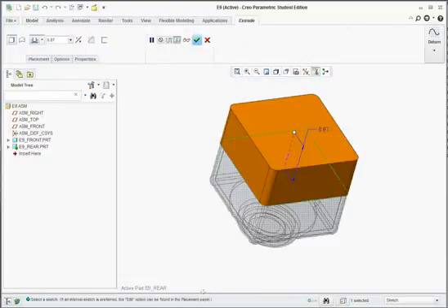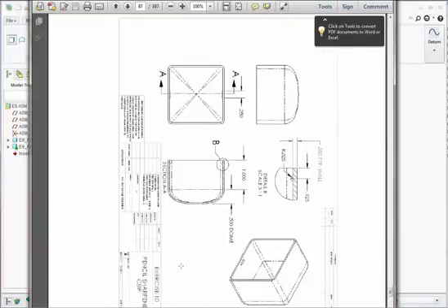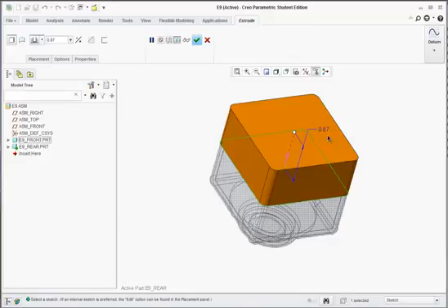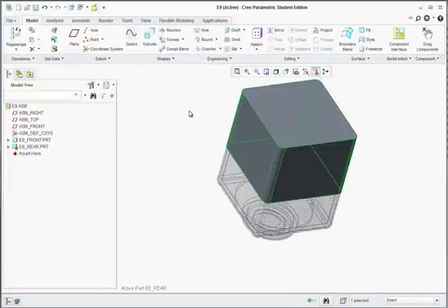Go to extrude, and now for the second part, it's going to be 1.5 inches thick, and it's going to have a dome radius on the back. So let's go with 1.5. And this is the reservoir, basically, what all the pencil shavings will fit in. We need to have it be able to come apart, but it will be big enough and easy enough to hold in the hand. So go ahead and hit accept.